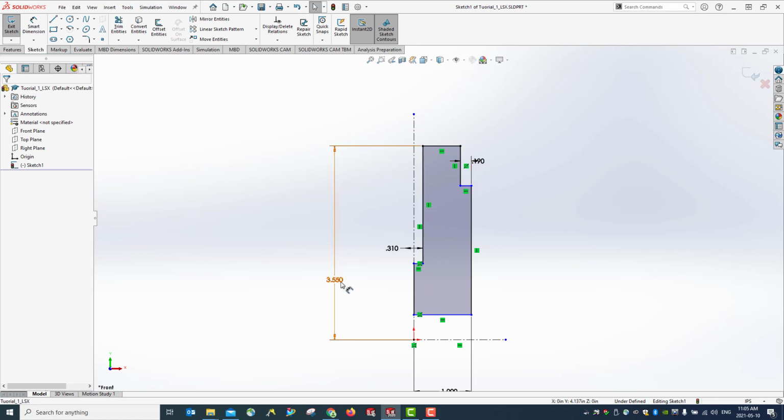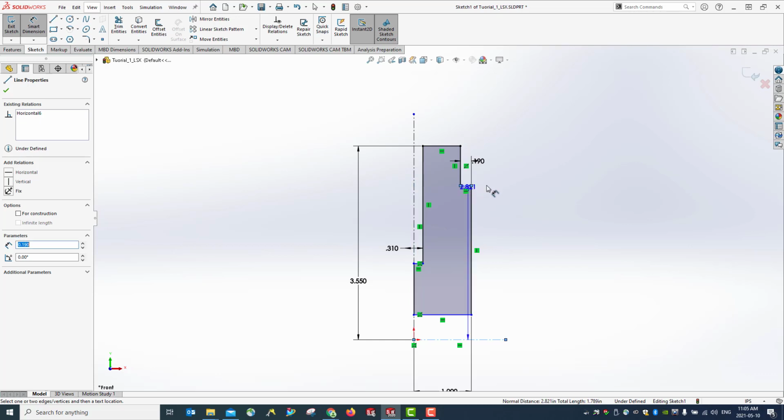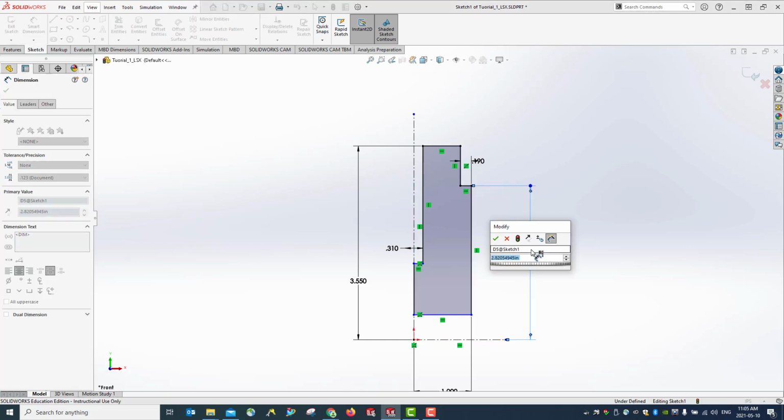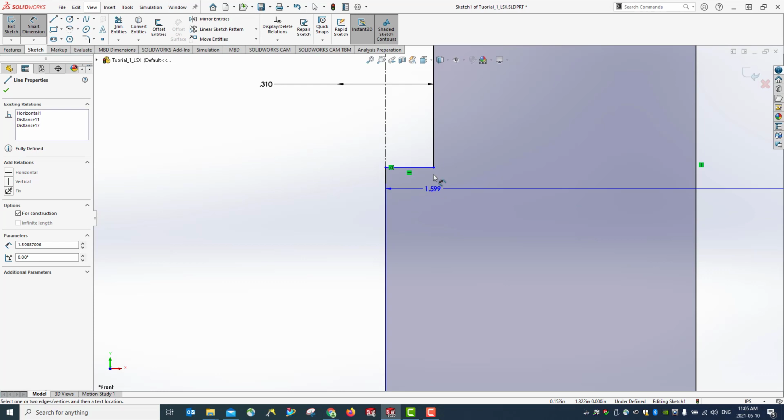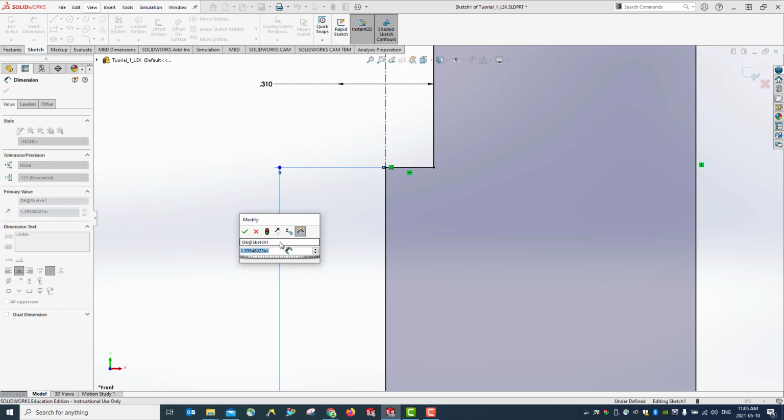So you can see here we have 3 decimal places showing in the dimension. Okay, so what's the next one? I'm going to use from here to here. The lower limit is 4.7, so 4.7 divided by 2. And we have the dimension for this step. This is the lower limit 3.52 divided by 2.